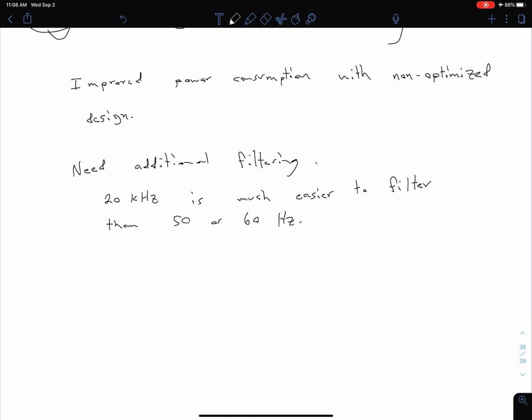And if you recall, what we talked about for filtering these frequencies with our brute force method is we have a capacitor and we have whatever the current is, but the capacitance is inversely proportional to our V ripple as well as the frequency of our ripple. So here we're talking about this frequency, so if that frequency is much higher, of course our capacitor needs to be a lot lower, and so that's a lot more feasible to do at high frequencies.